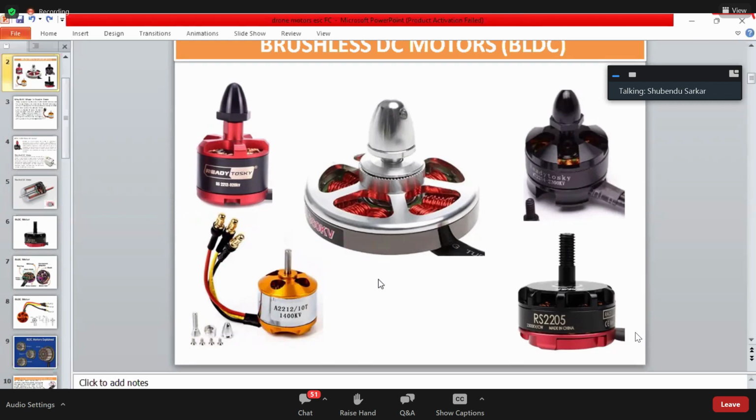So what's happening at that time? We are going to drag a lot of air through the wings. So if we want to drag a lot of air, we need bigger wings. Yes. But if we want bigger wings, the weight and the air resistance of the wing become very high. To overcome that, we need to make sure that my motor has a sufficient amount of torque, or the stator size should be in an appropriate match with the propeller.